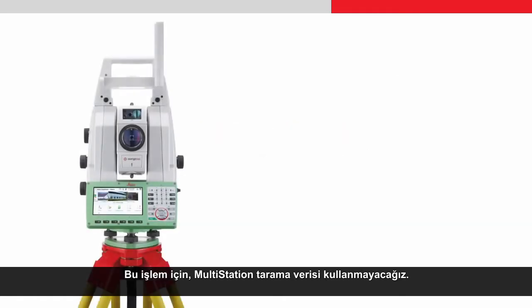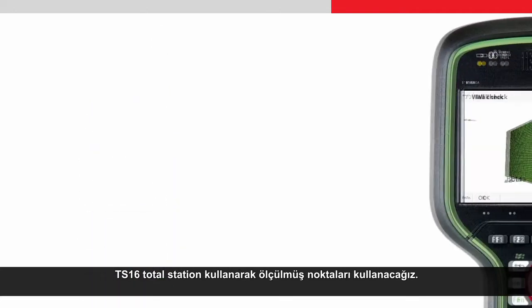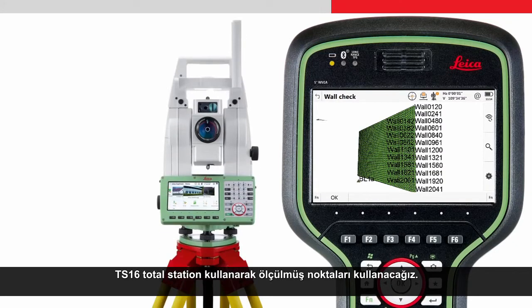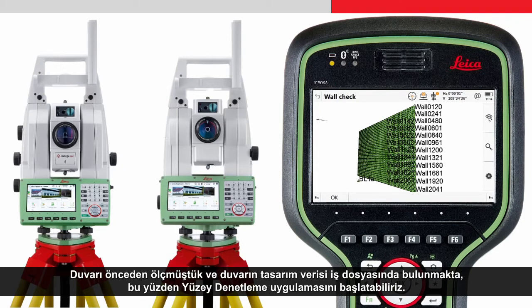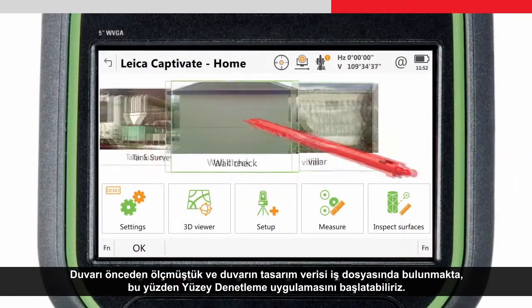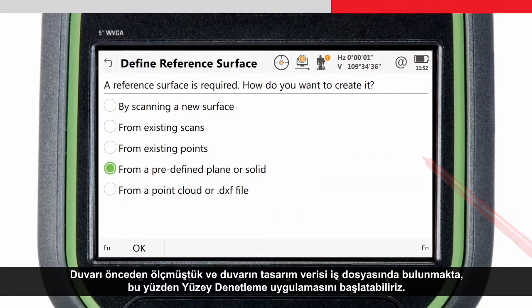For this task we will not use multi-station scan data. We will use a grid of points which were measured using a TS16 total station. The Inspect Surface app is not only for multi-station scan data, it can be used with any total station data, but more data can be collected more quickly with a multi-station. Again, we have already measured the wall and have the design data of the wall in the job, so we can start the Inspect Surfaces app.